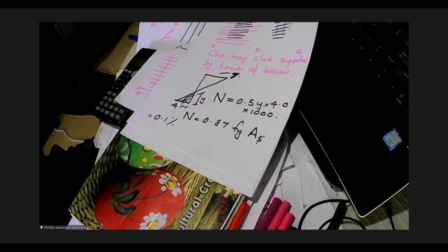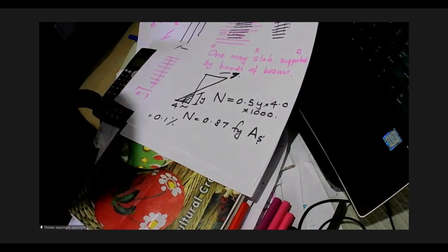T16 at 150 center to center over about 0.3. So that's how we provide some reinforcement over support at the column, and that will enhance the shear carrying capacity of the slab. But when you look at this, one thing you can see is this particular type of construction